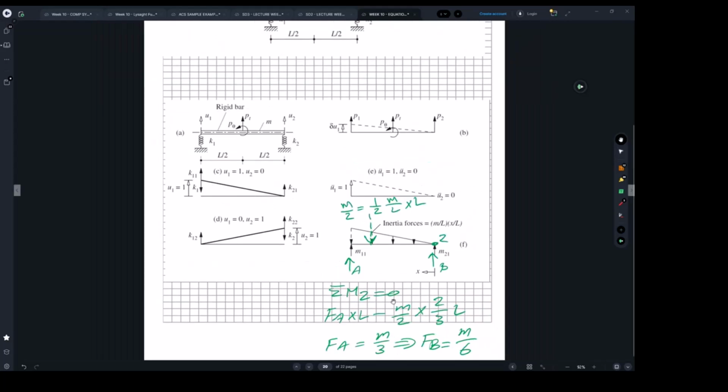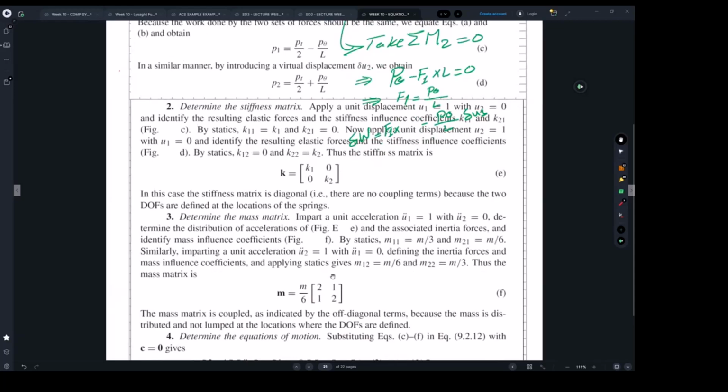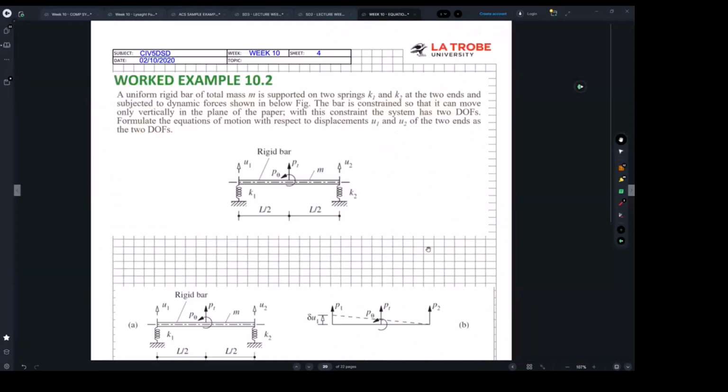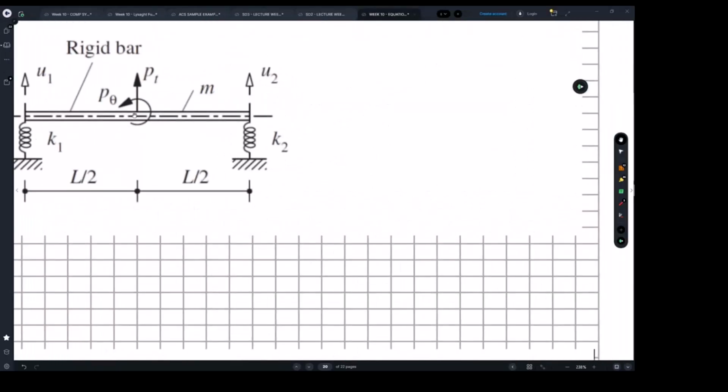So the skills, I'm sure you have them, because some students will come and ask me from where we actually find this one. Why we're not using the full mass? Why we're using 1/3 of the mass? We're using 1/3 of the mass because when we are applying load here in the rotation, we're not carrying the entire steel beam.